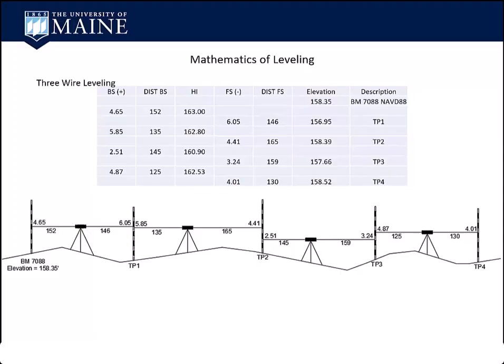There's other parts of standards that we'll look at a little later, but that's one of the advantages of the digital level. You can shoot your distances. If you were running it with an automatic optical level, you just pace them out, and you'd have to read them. And then if you had to move the rod back and forth, you did. It just took a lot longer.